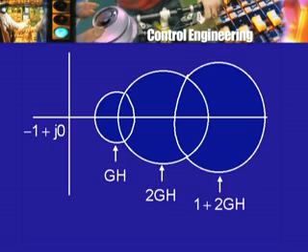And so, instead of talking about encirclements of the origin, which is what is involved in the principle of the argument, in the Nyquist method we talk about encirclements by the plot of KGH of the point minus 1 plus j0, and this is the reason for the special role that this point minus 1 plus j0 plays. And of course, as I told you, we really do not vary the gain in practice. So we have to find out the effect of the gain by simply considering scaling, and we will see how this will affect our calculations.